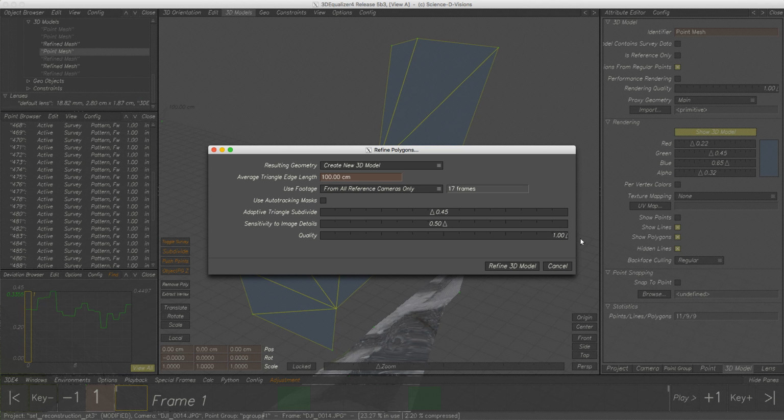Since the image quality is not ideal and 3D camera quality declines a bit due to the object's distance and image quality, the procedure should be a bit more tolerant towards artifacts and slight 3D camera errors. Further, the White Tower doesn't have many flat surfaces. There are setbacks, leaping bricks, everything seems to be crooked and uneven. That's a pretty hard task for refinement, so we need some tolerance for this unevenness as well. This tolerance is set with a lower sensitivity value.